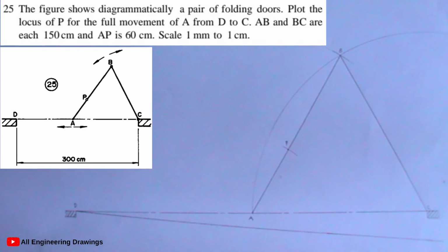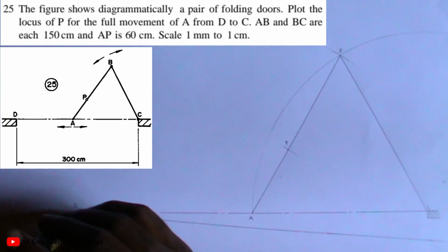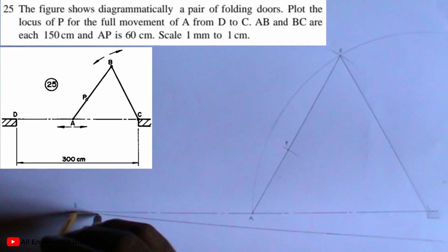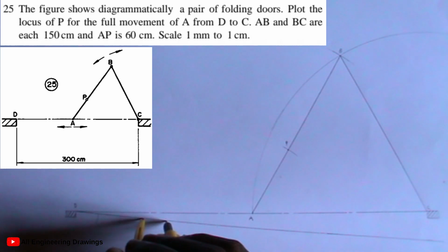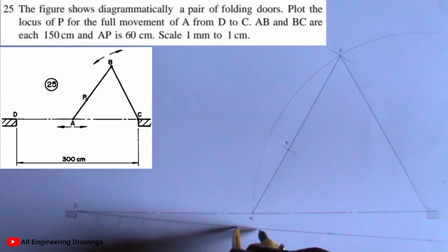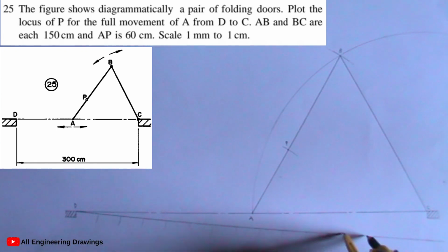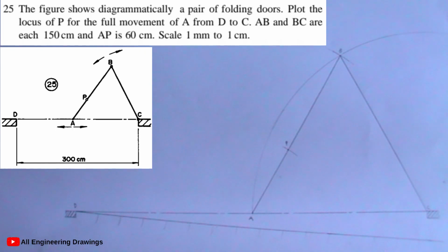After drawing the inclined line, I will mark off points of equal interval on the line. I'm marking off 15 points since I want to divide my line DC into 15 equal parts. The radius I use can be any convenient radius. I will place the compass on point D and start. Now this is it, we have our 15 points.